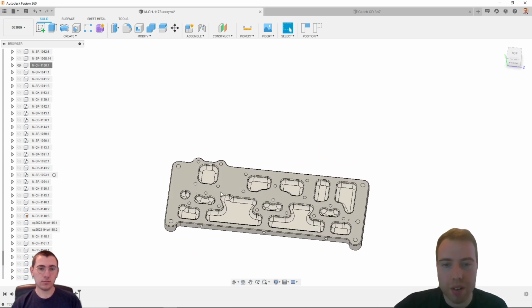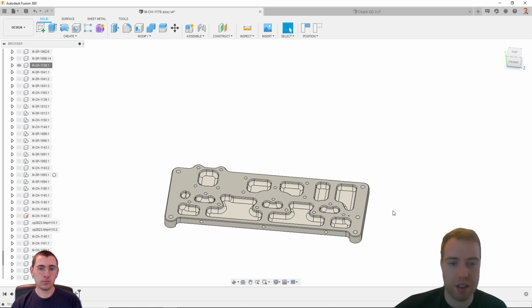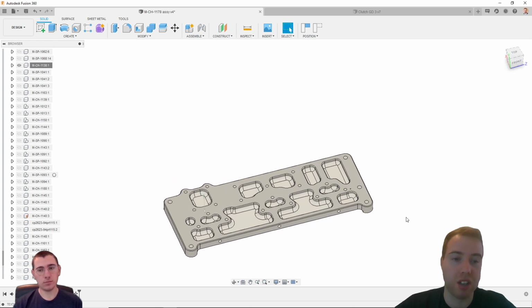So we can see the shape that we've got here obviously has certain functional components that connect in with other elements of the assembly. And also what we've done is taken material away, often for lightweighting purposes. If this is a subtractive manufactured component, we're deciding to add cost to our manufacturing process to take material away, and in doing so, we're wanting to add value to our component. In this case, some of that value comes from lightweighting.